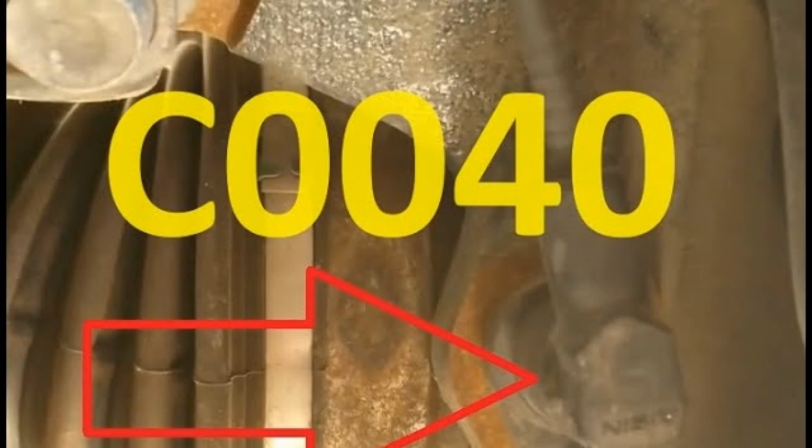Wheel speed sensor circuit problems. Problems in the wheel speed sensor's electrical circuit, such as loose connections, cut wires, or short circuits, may cause the code to be recorded. Problems with relays or wheel bearings. Problems with relays or wheel bearings can also cause malfunctions in the ABS system, leading to the detection of fault code C0040. Problem with the ABS module. The ABS module itself could be faulty, resulting in the code being recorded.